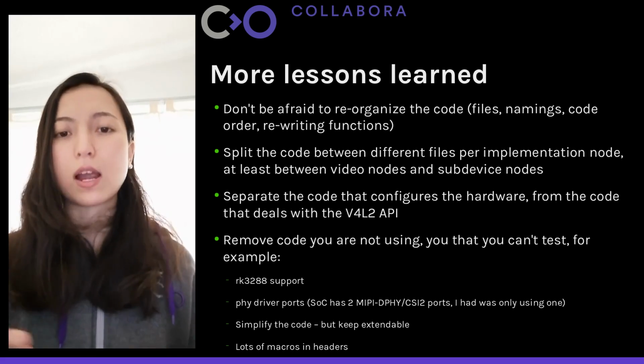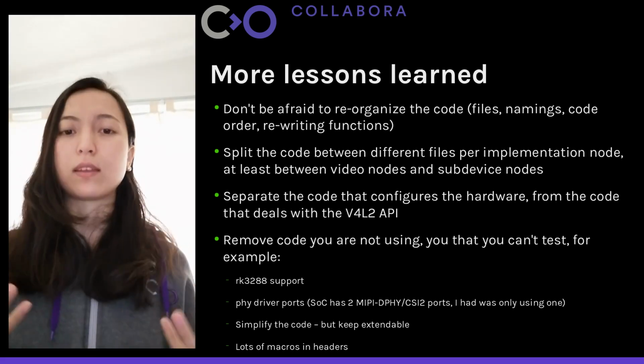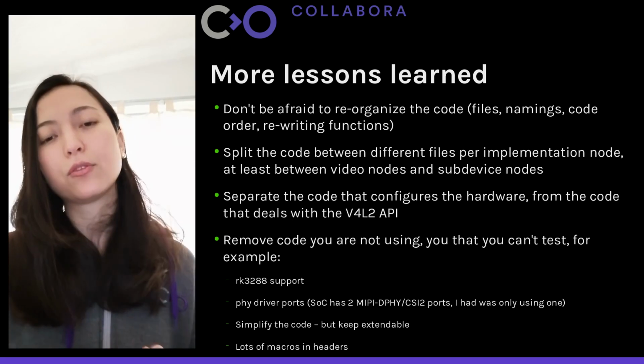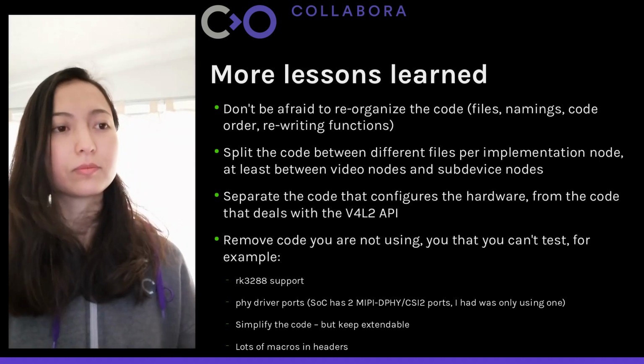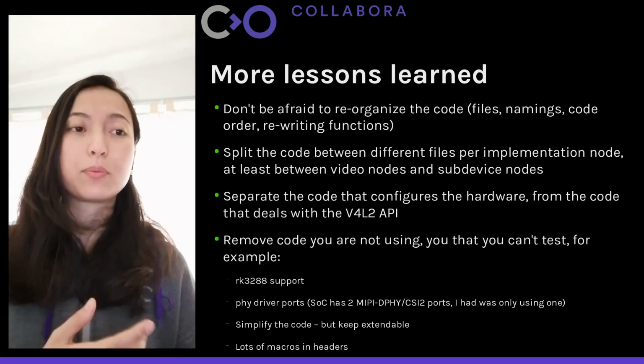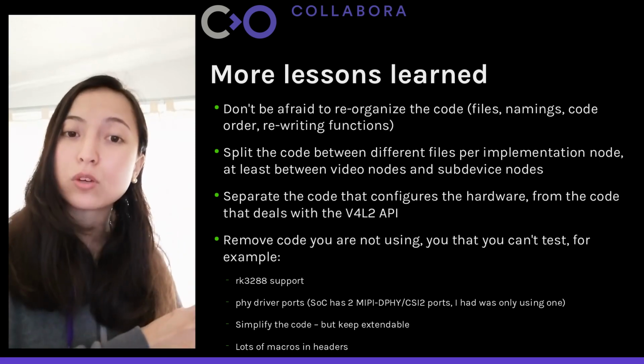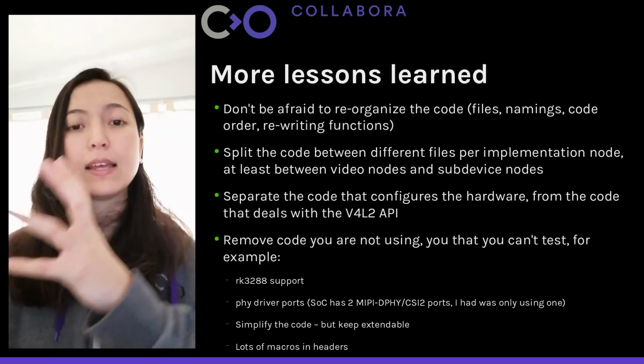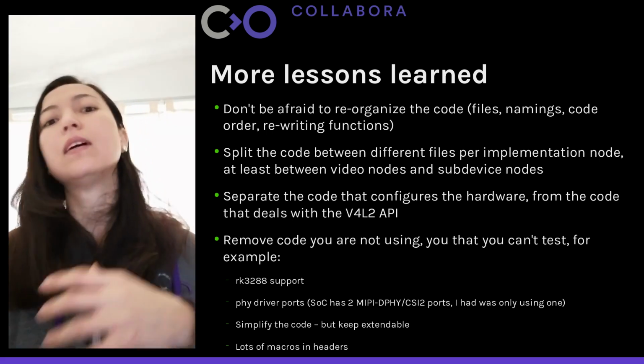Of course, those are all tips. Take it with a grain of salt. Check if those apply to your case. I would also separate the codes that configures the hardware from the codes that implements the Video for Linux API.